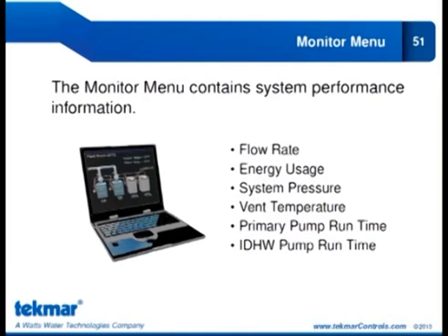50, 100, 150, 200, and 300, I believe. You select that model, that range, then you connect it up. It's a 4 to 20 milliamp pressure sensor. So again, we provide power to the sensor and the feedback signal. So we get to basically display gauge pressure. And of course, that then can be communicated over the gateway for display on the web.